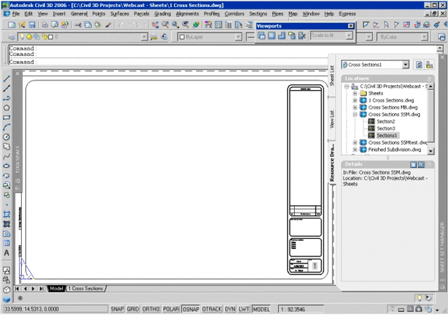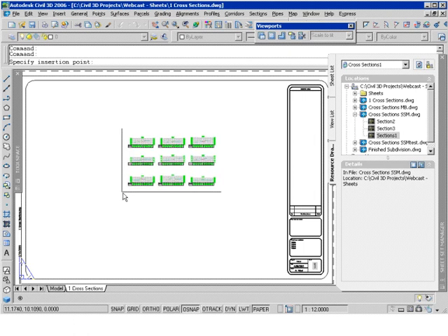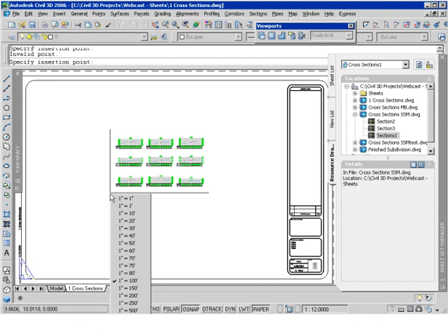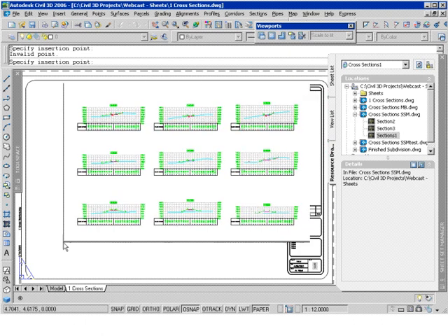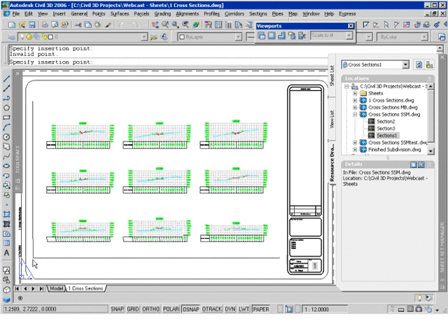this new drawing. What's going to happen here is it's going back to that resource drawing, looking at that AutoCAD view, and is actually going to create a viewport in my current layout for that view. And what I can do is right-click here upon insertion and actually pick a scale for that viewport. So in this case, I want to work with 1:40.